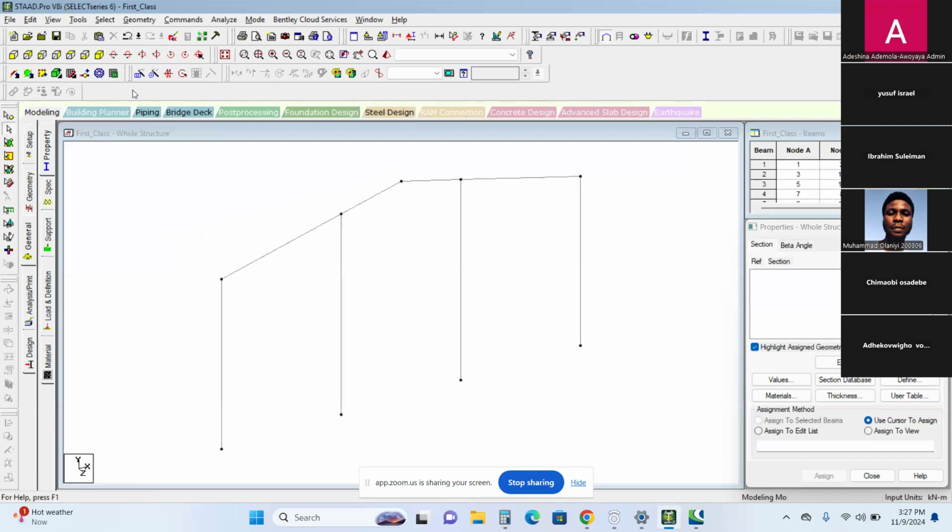Now, this warehouse, if you're into steel construction, you observe that most times in a warehouse, the first and the last bay are usually maybe 4 stanchions, some maybe 6, whereas the spans at the middle are always 2. So let's say we want to copy this whole thing now, 5.5 meters towards our Z axis.